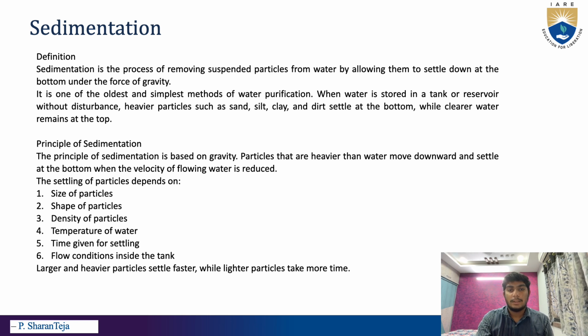Principle of sedimentation. It works on gravity. Particles that are heavier than water move downward and settle. The settling speed depends on the size of the particle, shape of the particle, density of the particle, temperature, flow condition, and time given for settling. Larger and heavier particles settle faster, while smaller particles need more time. Sedimentation is usually the first step in water treatment.